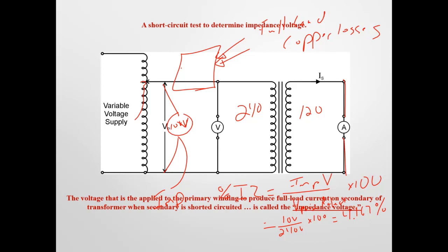It may not function properly. They're not rated to interrupt that high of a fault current, right? So the 15 amp rating, that's its continuous rating. So if I put too many lights on, or the motor draws too much current, that may trip that fuse at 15 amps as soon as we approach near that.